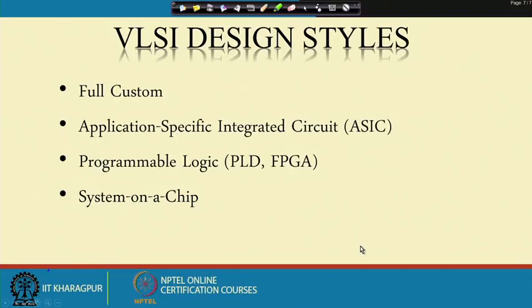Now, VLSI design styles. There are different styles in which you can implement your circuit. One of those is full custom design, then semi-custom design or application specific integrated circuit, then programmable logic, that is PLD or FPGA, and then another is system on a chip.